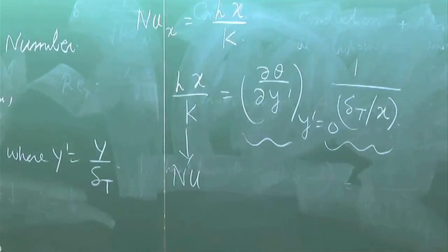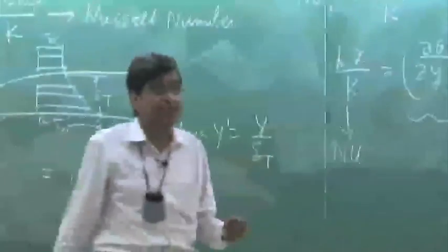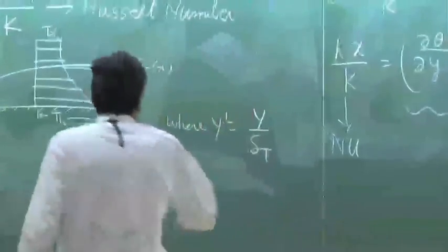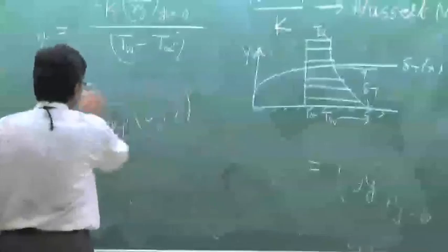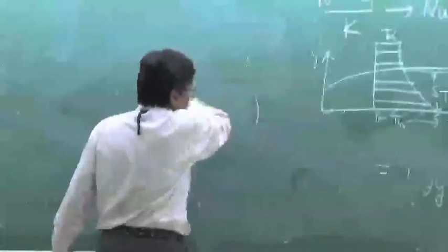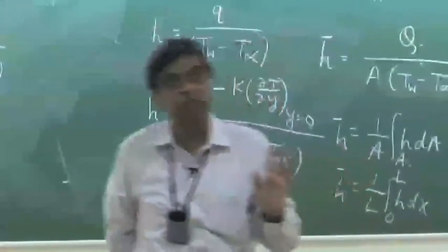If we consider the flow to be incompressible, whose velocity is relatively much smaller compared to sonic velocity, and we discard the flow of fluid through a very narrow channel, for example in a micro channel or micro tube where the strain rates are very high, we can discard the viscous dissipation.